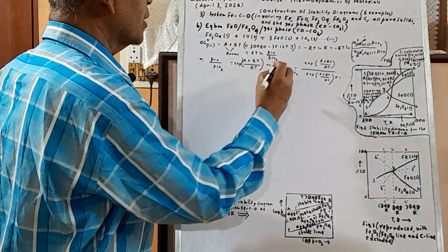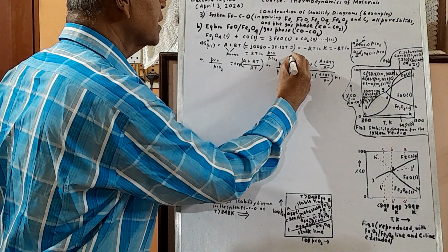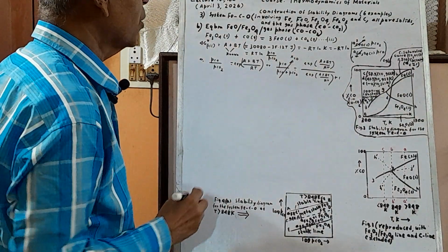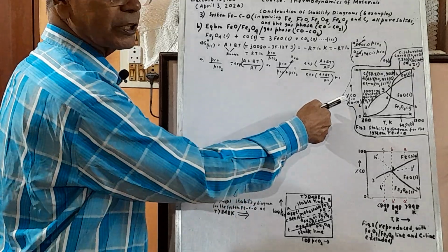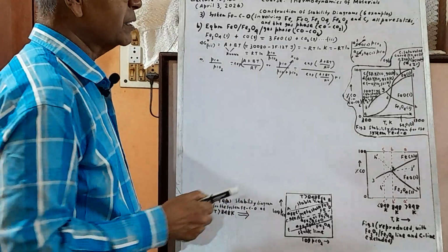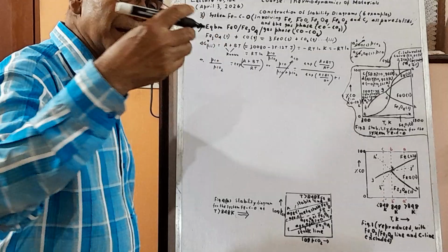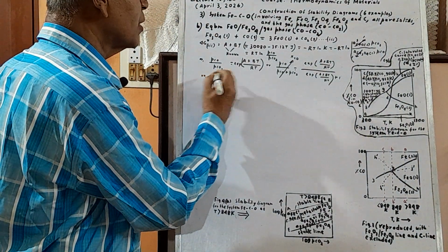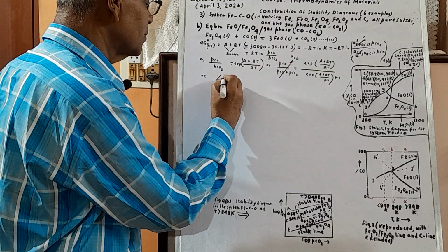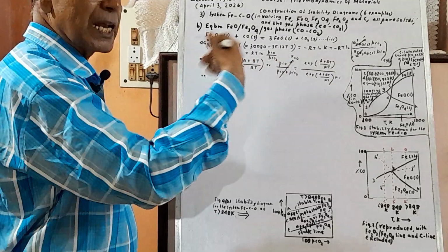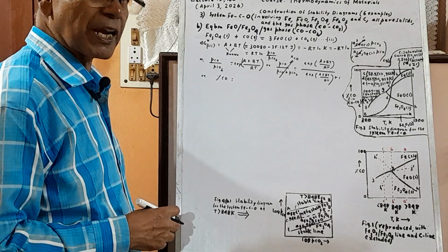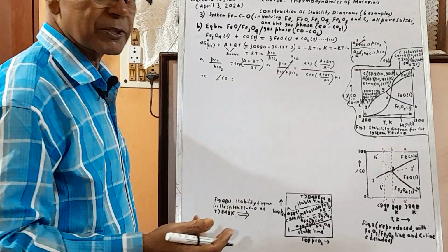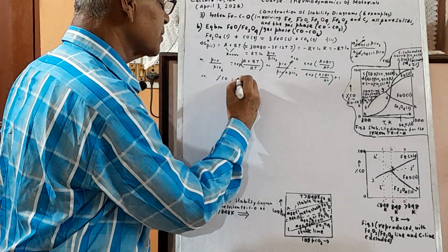What is the name of this? You recognize this is the mole fraction. So percentage CO is plotted. This is totally an equilibrium diagram. Stability diagram means equilibrium diagram. Percentage CO is 100 times X CO, where X is the mole fraction of CO in this CO, CO2 mixture. The mole percent is 100 times the mole fraction.